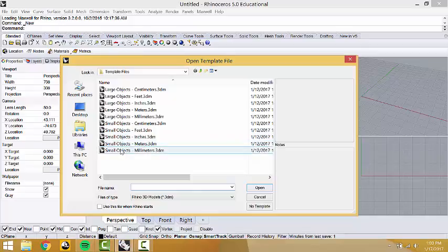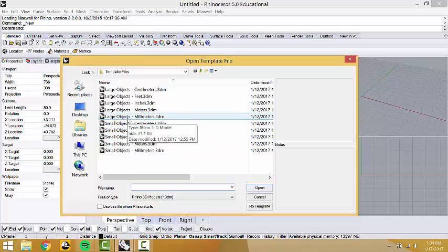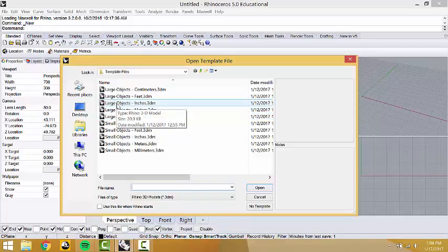If you are modeling a small object, like a couch maybe, or jewelry, it's clearly small objects. Small objects in meters is basically never used. The architecture comes in at large objects almost always. Metrically, we're probably going to do this in inches. As architects, we almost never model in feet because technically that would be feet and then always a division by 1/12, and then things get weird. So usually at the scale of architecture, you model in large objects, inches.